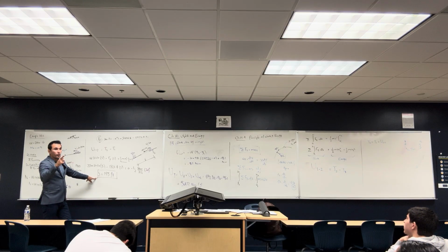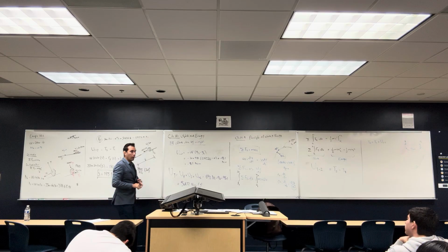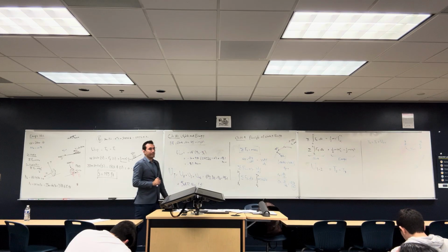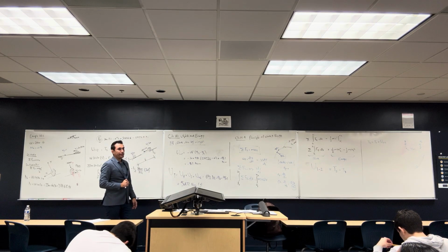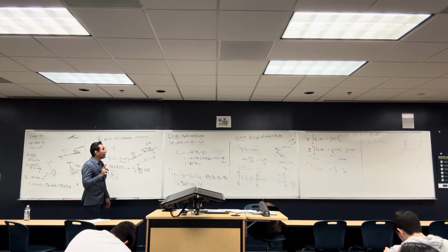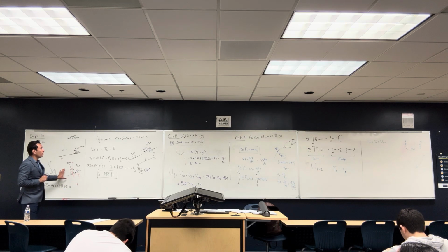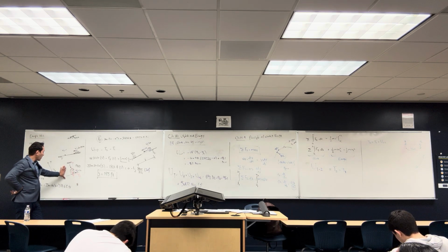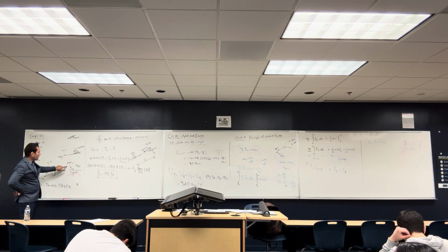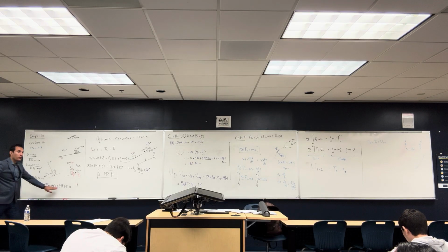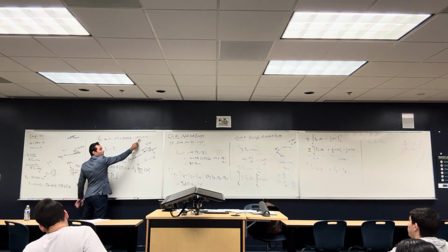Yeah. You have a question? Sure. To find the friction force, is it possible to solve for N with the y component? Yes, so for the normal force, using the y component, and then use N to find the friction force. But that's what we did here. Here's the weight, and we got N here. We got N minus W cosine 10 equal to 0. And then once we got N, we multiplied by mu K, and then we got the F of friction.